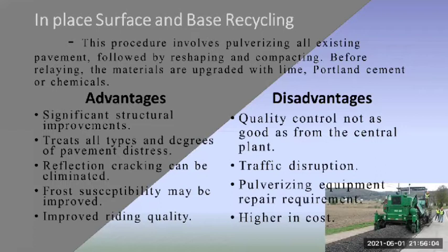The main advantage of in-place surface and base recycling is that it increases the load carrying capacity of the pavement. Advantages: significant structural improvements. It treats all types and degrees of pavement distress. Reflection cracking can be eliminated. Frost susceptibility may be improved.